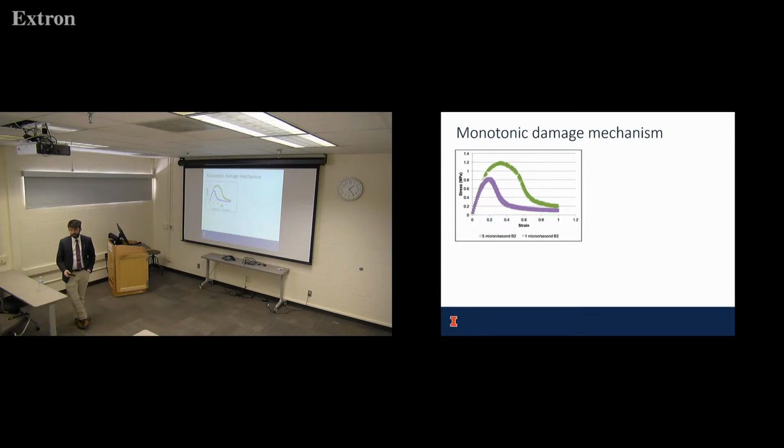binders. So did you see much more cavities forming, like more frequently in aged binder? Yeah. No, I would say no. Like the same number? Yeah, the cavity size and shape and number of cavities all probably depend most on the base binder, choice of base binder, rather than any kind of aging, loading rate, or temperature. A PAV of a specific binder looks more like the RTFO of that binder than the PAV of another binder. So.